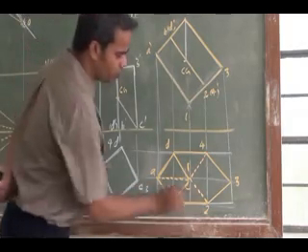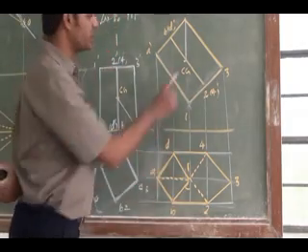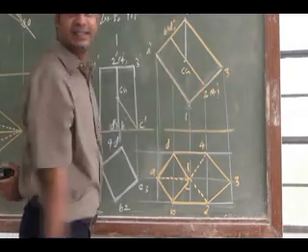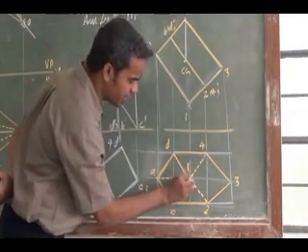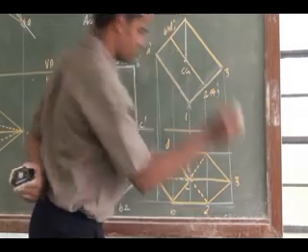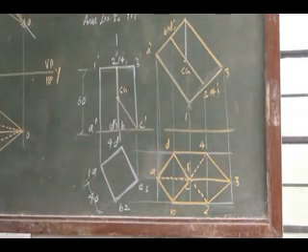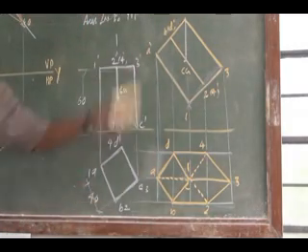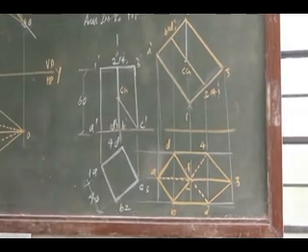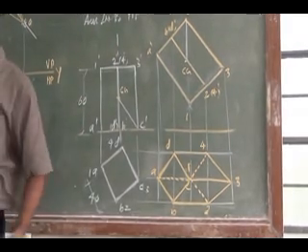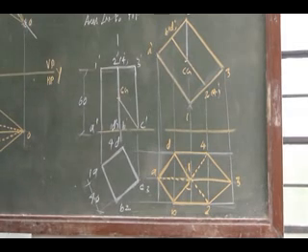So already I have B2 visible, D4 visible, and one more thing is C3. C3 will be visible. So C I have here, C3 will be a visible one. So this is how your top view would be. Right. For this you have to carefully follow your note to show the visible and hidden details. Right. Do this as a homework.